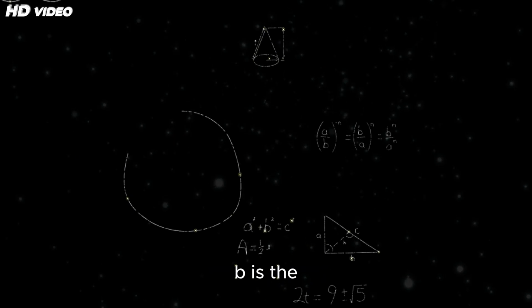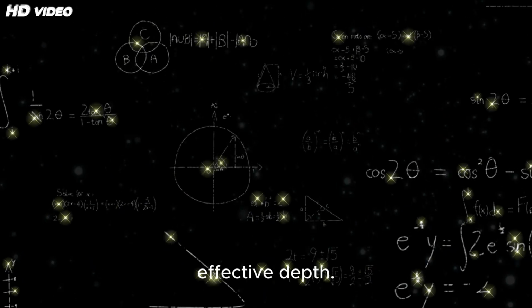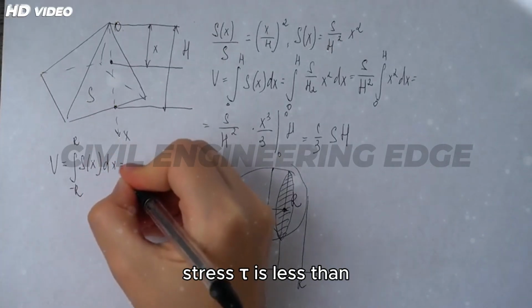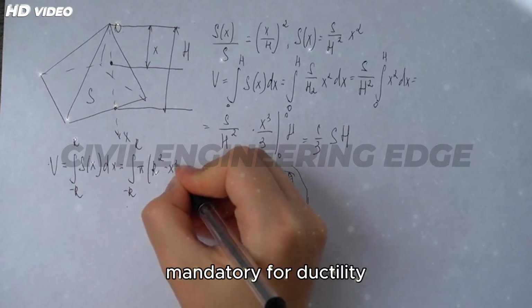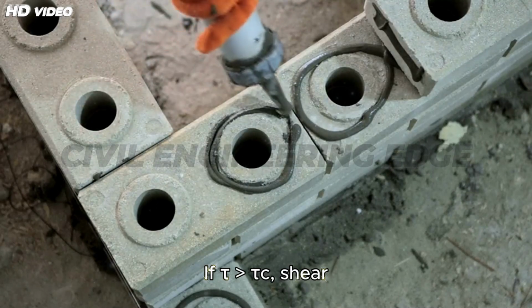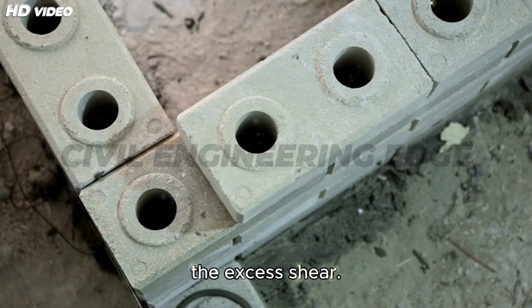Where Ast is the area of tension steel, b is the breadth, and d is the effective depth. If the nominal shear stress tau v is less than tau c, no additional shear reinforcement is required, though minimum reinforcement is still mandatory for ductility and crack control. If tau v is greater than tau c, shear reinforcement must be provided to resist the excess shear.